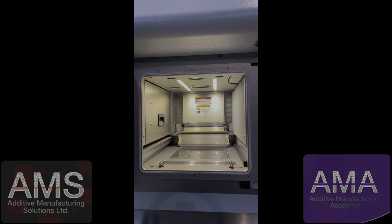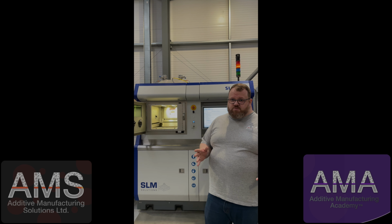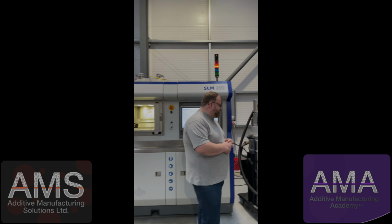Now let's zoom back out and have a look at how we handle the powders in the system. So right there were the fundamentals of the laser powder bed fusion process. The powder is really key. We mentioned already how the powder is fed into the system. What we also need to ensure we understand is how we handle the powders. Powders in the additive manufacturing process will often change. I always describe them as the dynamic part of a fixed process. So to make sure we stop any of these changes from having an adverse effect on our parts, we normally make sure we sieve to remove all the very large and the very small particles. Come with me to have a look at our sieve capability.